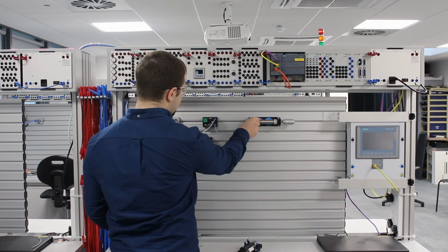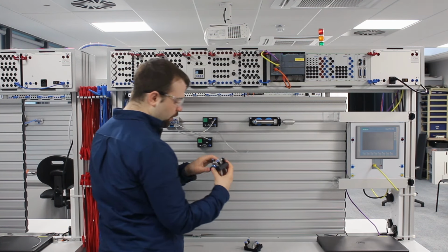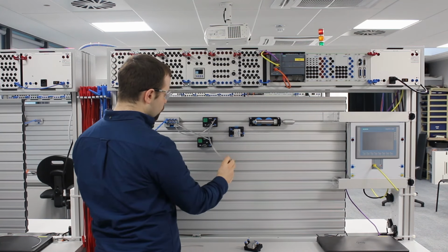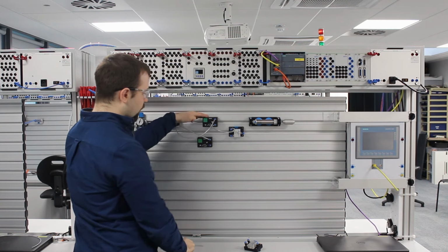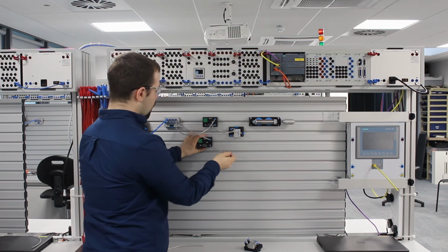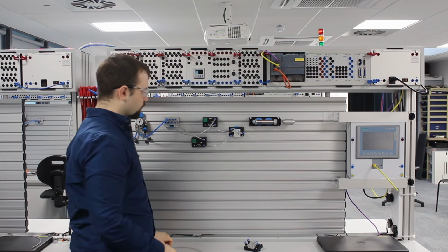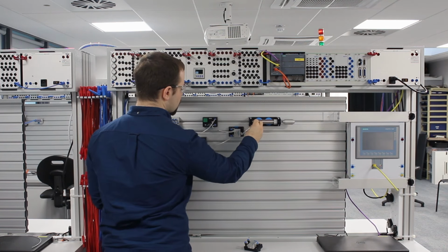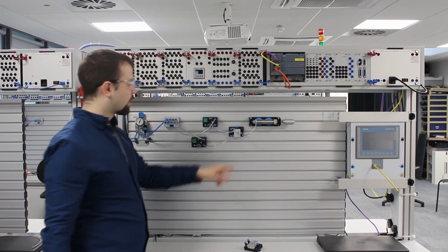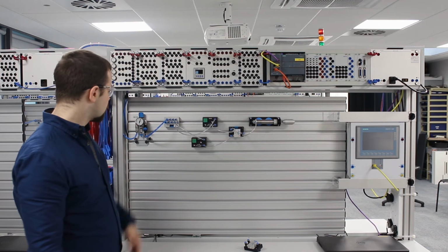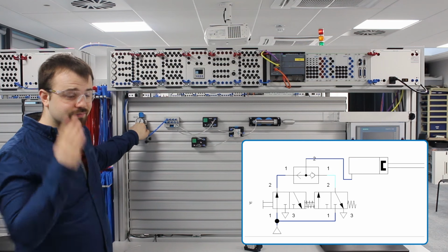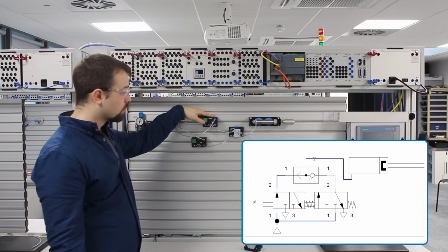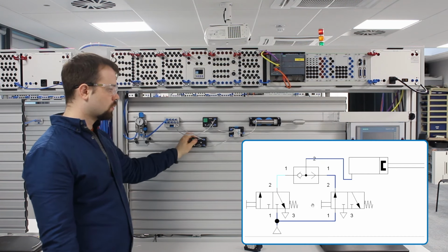I'm then going to take the air out of the top one and we're going to work with the OR gate first. So I'm going to clip the OR gate on and put one pipe from the first button into the top and one pipe from the second button into the bottom. Then I'm going to place a pipe finally into my cylinder at the end. So now I'll turn on the air, goggles on, nice and safe, and I can push either button to make the cylinder move. 1 or 2.